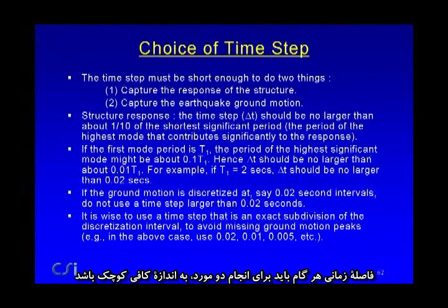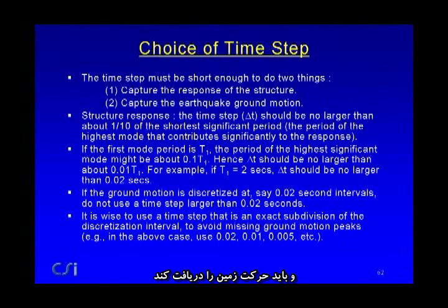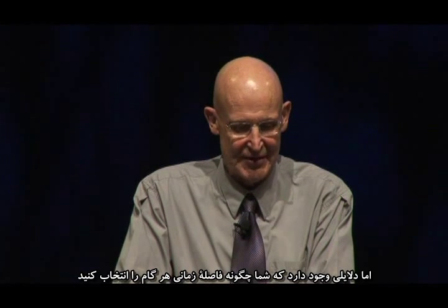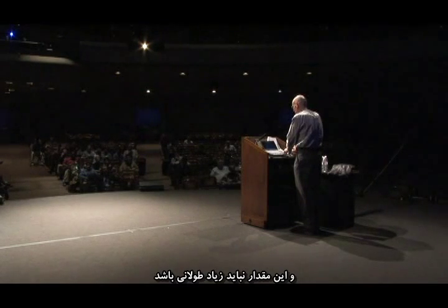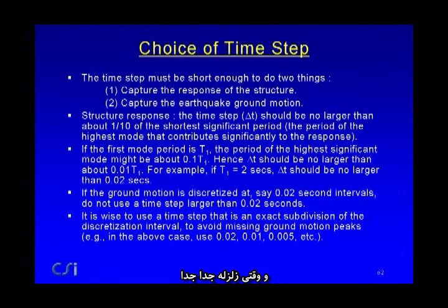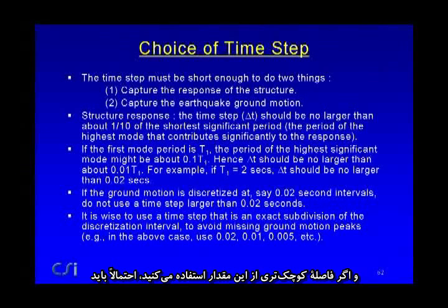Choice of the time step. The time step must be short enough to do 2 things. It must capture the response of the structure, and it must capture the earthquake ground motion. I'm not going to go into this, and my voice is getting tired, and you're getting tired, but you can take a look at this, which gives some indications of what you might do to choose the time step. It shouldn't be too long, and if the ground motion is discretized at, say, 0.02 seconds, you shouldn't use longer than that. And if you use shorter than that, you probably should use a whole divisor of 0.02 seconds,